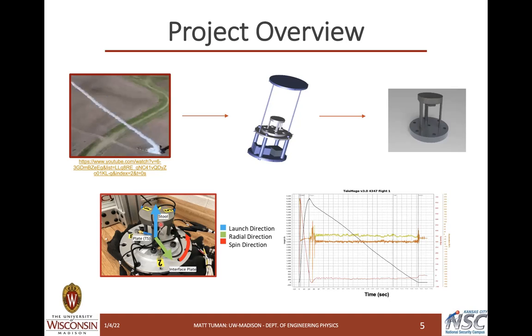For this assembly, the stool is our subcomponent and the plate is the transmission simulator because the stool is only attached to the plate. For this launch, 3 triaxial accelerometers were used to measure the response of the plate, and another 3 triaxes were on the stool, which recorded the response during launch. This subassembly was then sent back to us, and we try to recreate the responses recorded during launch.